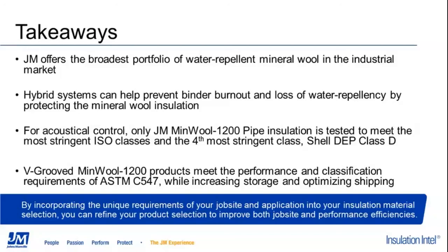As Natalia has described, you can utilize a hybrid configuration to allow you to take advantage of some of the excellent benefits of the mineral wool system, whether it be low cost or water repellency, or maybe it's acoustic performance, without having significant concerns about any loss of performance as a result of binder burnout or losing any of the water repellent capability. So ensuring that the mineral wool can continue to deliver the benefits it was designed for throughout the life of the installation.